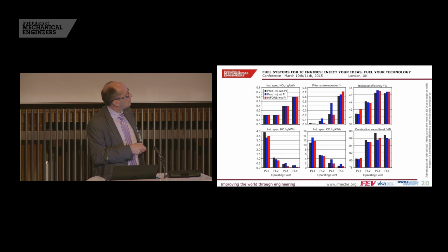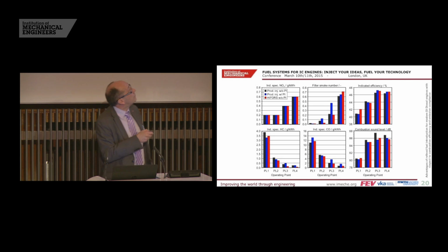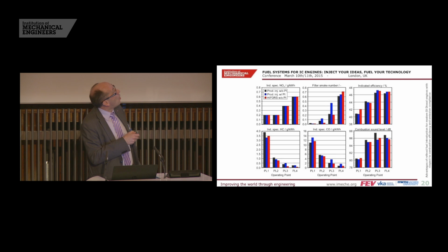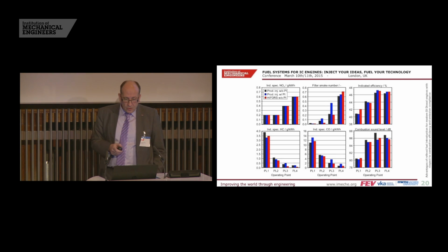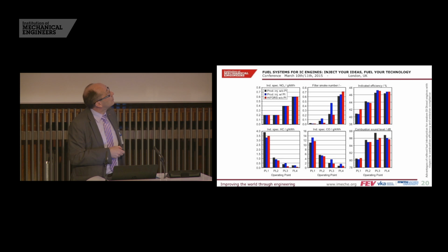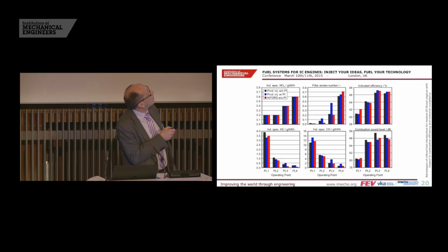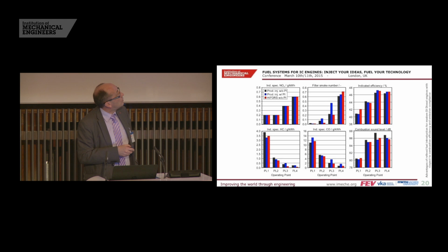So we have here, as a function of the different operating points, starting with the light load operation, going to the medium speed, high part load operation. We have plotted and summarized the results, always adjusted to the same NOx output of the engine, so the specific NOx emissions are always comparable. And then we see different results from the different strategies which have been investigated. Once again, we have the production injector without and with pilot, and the high force injector without pilot in contrast. And you see that depending on the load point, there are slight differences.